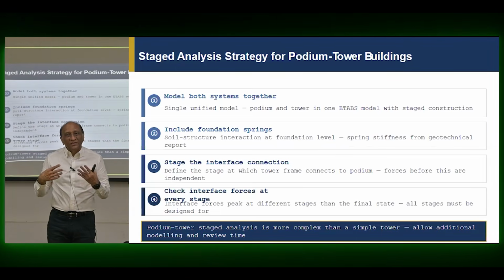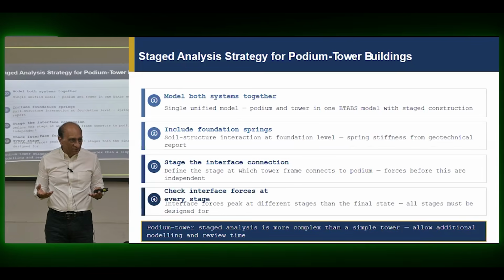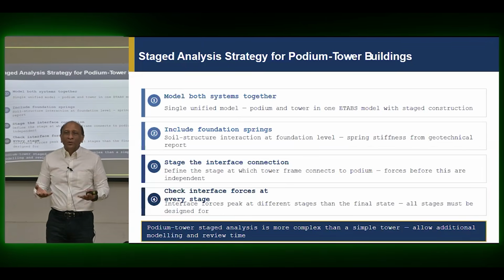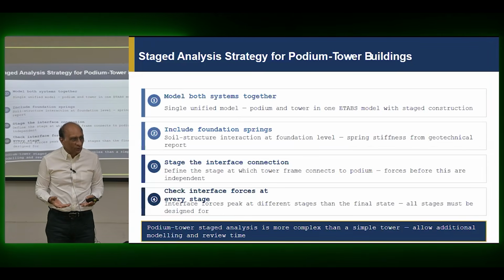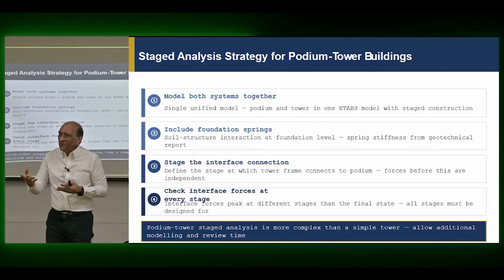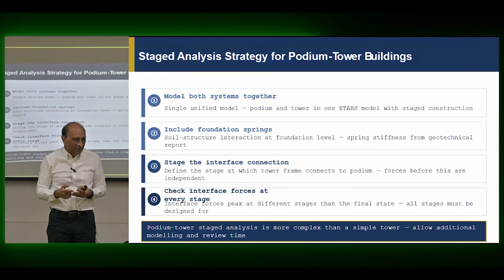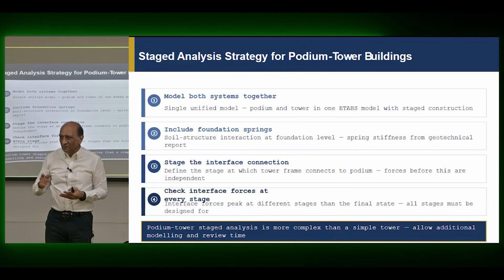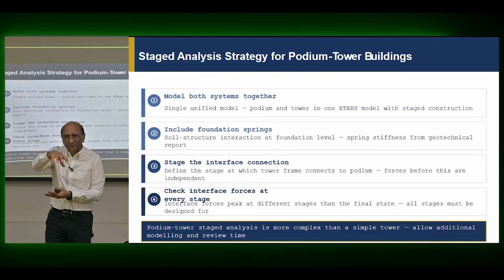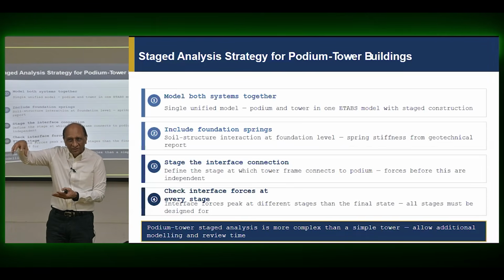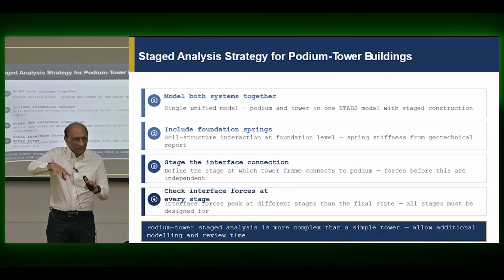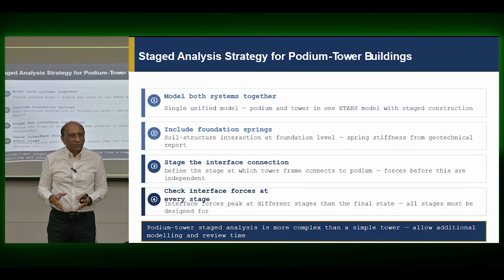Plus, you can transfer the deformations also, because we can do that. Then you run the podium analysis for those forces, and you can run different scenarios: only one tower constructed, two towers constructed, three towers constructed. You just have different load cases for each tower being constructed. Then you can understand what's happening to the podium.